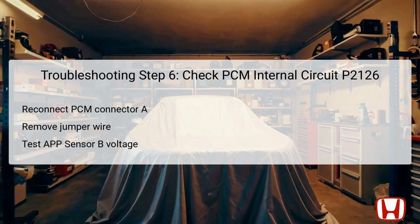First, reconnect the PCM connector A, 51P, and remove any jumper wires from the APP sensor. Then, connect the terminals of the APP sensor's 6P connector to check the performance of APP sensor B by measuring its voltage. Activate the vehicle to the on mode again and validate if the readings from APP sensor B fall below 0.19 volts.